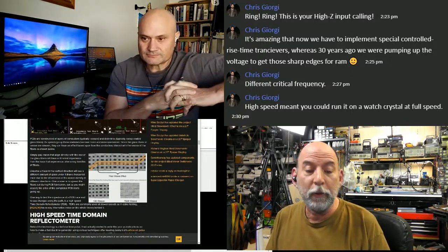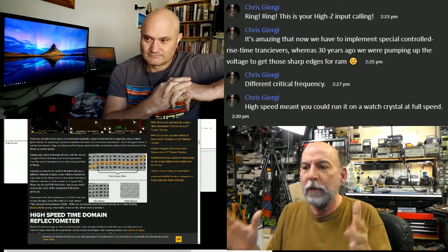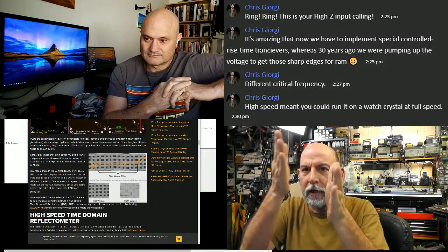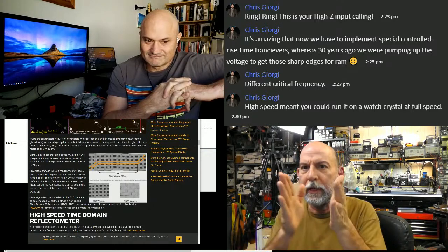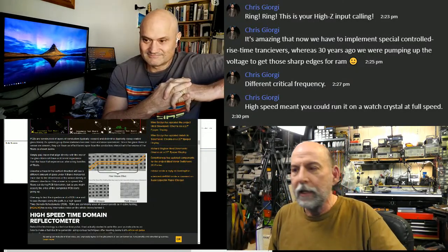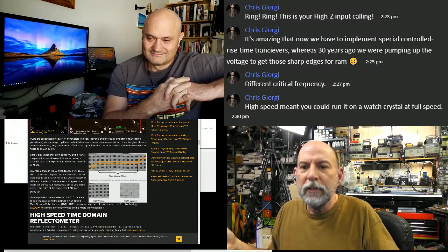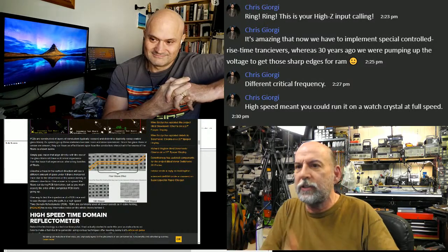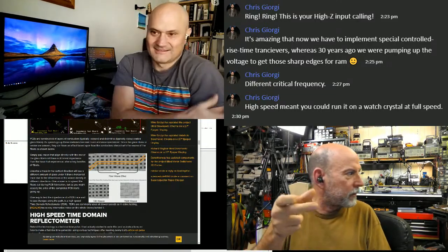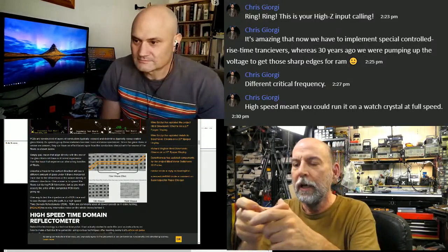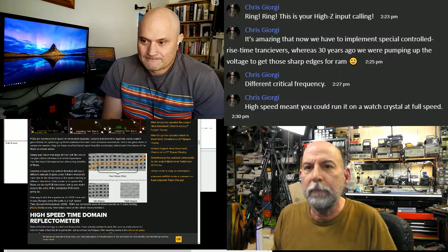Actually the 128, we had an 80 column chip. It was 1 week before CES. And the 80 column chip was trying to work asynchronously, and they didn't try to synchronize it with flip-flops. I asked the guy, so why didn't you try and synchronize, which means to keep clocking it until it's clean? And he goes, well, statistically, even a certain number of these stages will still fail. But it's like one every 300 years instead of once a second. So I had to make the show, we used a 4046 phase lock loop in a little tower that sometimes I have laying around, and made it so it ran off the same frequency as the VIC chip, the 40 column chip.